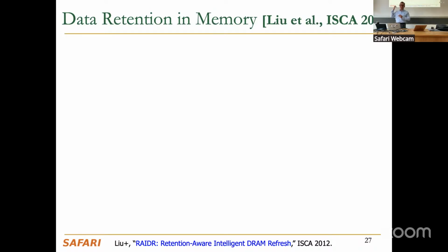We're going to see how exactly it's done. It's done using some commands from the memory controller. You inject charge back into the cells periodically. The question is, how often should you inject charge back into the cells? That's a key question, basically. Because if that is not often enough, you may lose the data inside the cell. If it is too often, you're replenishing the charge too often, meaning you're doing this additional refresh operation a lot, which is wasting energy, and wasting performance because you cannot access the DRAM cell while you're replenishing the charge in it. So that's the fundamental problem.